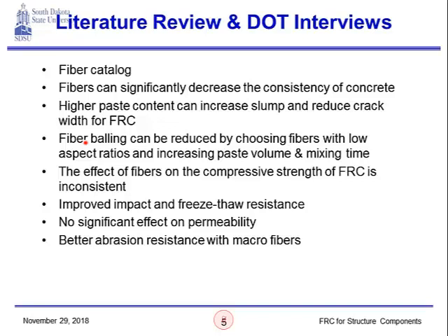Now, fiber balling can be reduced by choosing fibers with low aspect ratios and increasing paste volume and mixing time. This is something that we actually did in our laboratory tests here. We increased the mixing time in order to make sure we eliminate any fiber balling and make sure that fibers will really act as they should in the final product. Also increasing the paste volume, as I said, would reduce the fiber balling, and specifically choosing fibers with low aspect ratios can also help in making sure that we eliminate this problem.